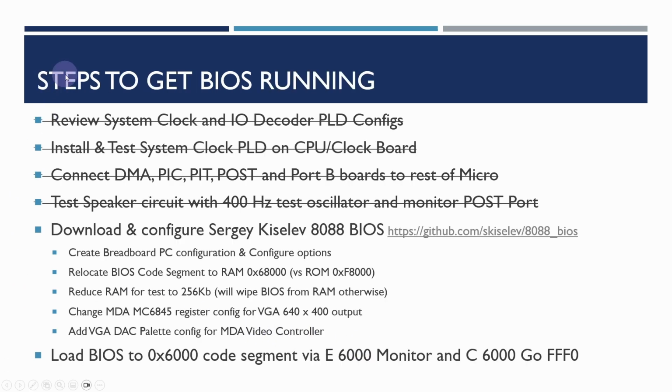So in the previous video we covered a number of these steps already, including testing the hardware output of the speaker circuit. What I'm now going to do is to show you what I did to download and configure Sergey Kiselev's 8088 BIOS, which is available on GitHub here. What we're going to be doing here is creating a breadboard PC configuration and configuration options. You'll see there's a number of different models of PC supported by the BIOS.